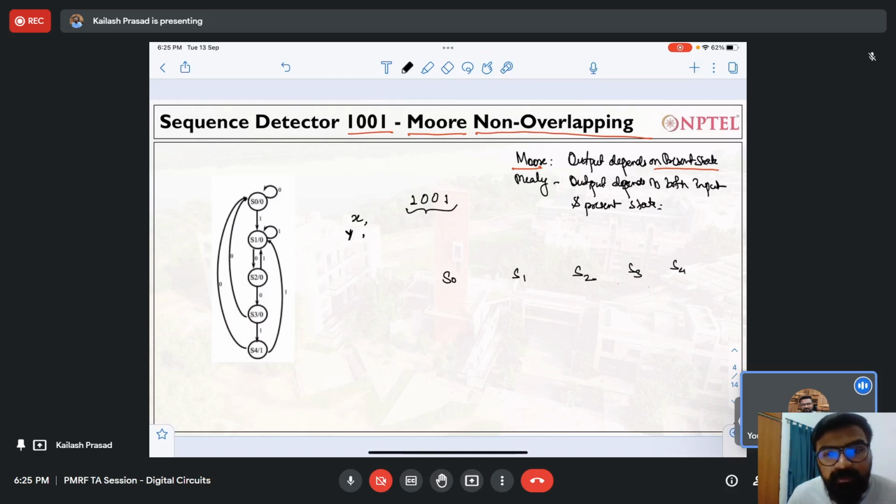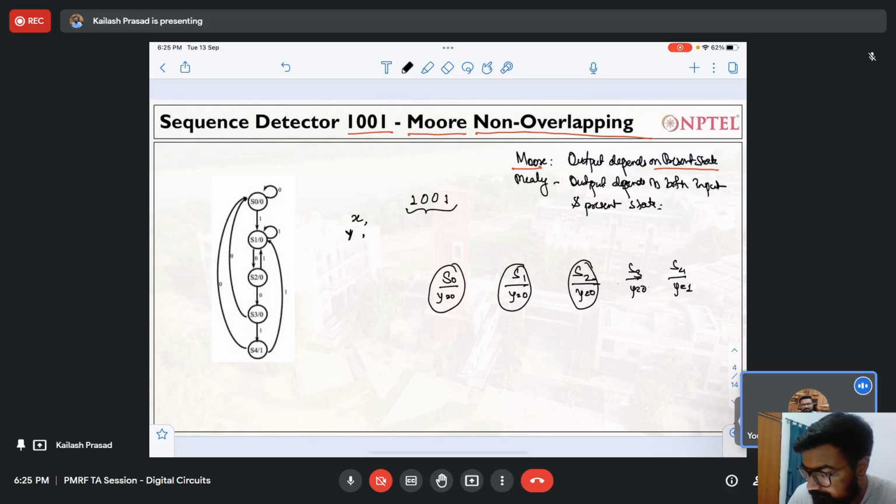What does the output of each state represent? Because this is a Moore machine, every state has some output corresponding to it. For this state, Y is equal to 0. For this one also Y is 0. Here also Y is 0, and here also Y is 0. Here Y is equal to 1. If you get to S4, it means Y is 1. So I will make these states. Very simple.